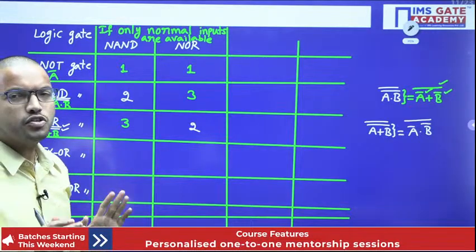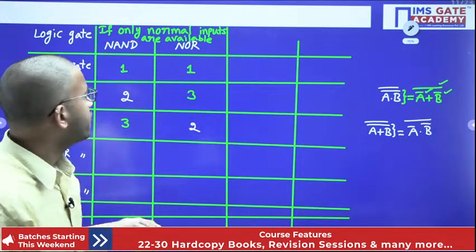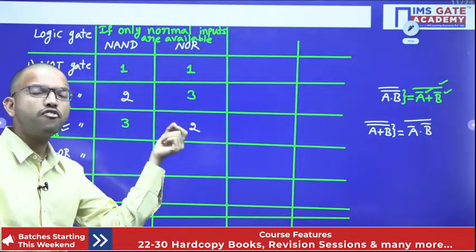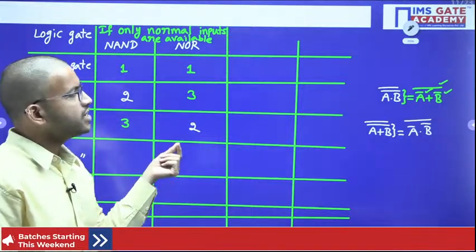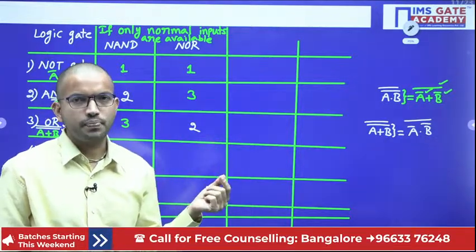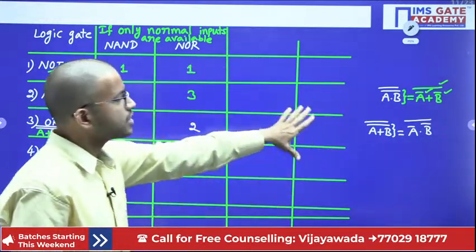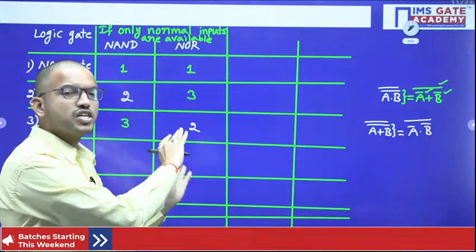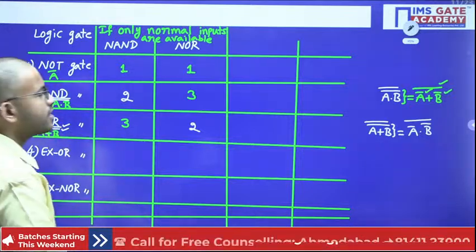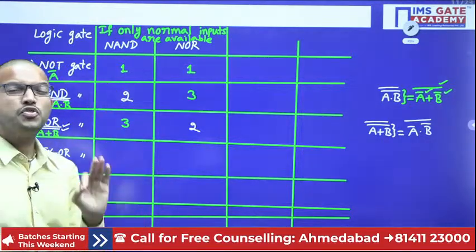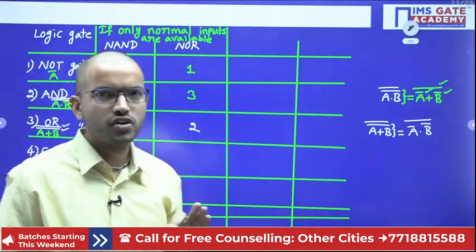And if you want to represent it another way, in terms of Boolean functions, whenever you have the original Boolean function, after doing the simplification you will get what? You will get either SOP form or POS form. Regarding this also you can easily understand, and I will give the conclusion point or brief summary with respect to SOP and POS also in some time. Okay, right. So either with the help of that logic or with the help of this logic, you can answer any question regarding the minimum number of NAND gates or minimum number of NOR gates required.